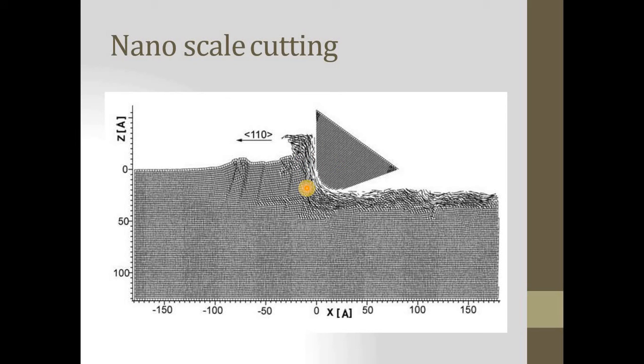The lower energy requirement for twinning makes the chip removal process at larger cut depths more efficient, and the cutting forces only increase proportionally. Here are two subsequent 2D views of microstructural snapshots of the same model as shown in this figure, but at a smaller cut depth